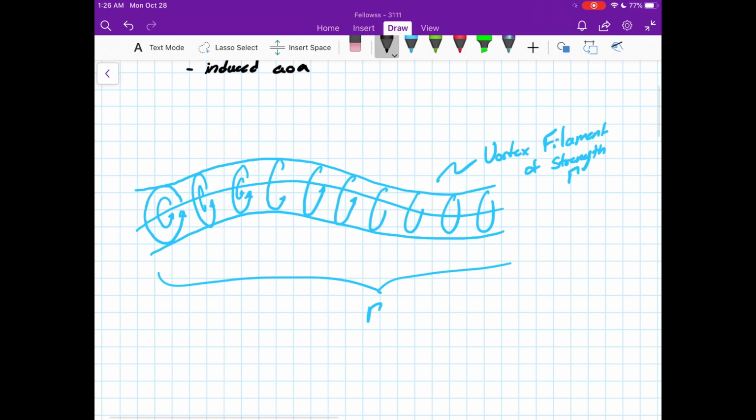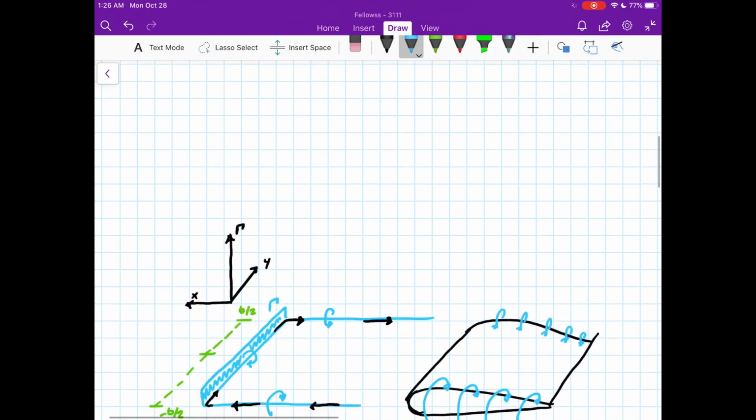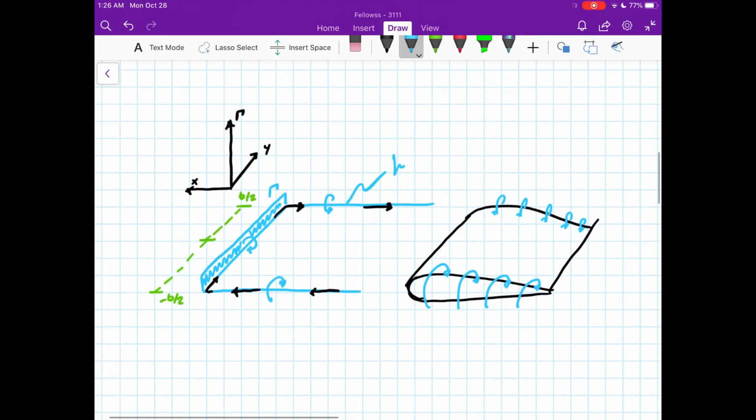So usually what we use is vortex filaments, right? What I have drawn here is essentially a 3D vortex. We started out with vortices that were just these planar guys, and essentially we've stacked them up and put them in a line. With that, we twist them around and shape them into horseshoe filaments, right? You can see I've drawn the direction we've put them in right here, and this gives us a wingtip vortex-esque swirl on this side and the same on this side.